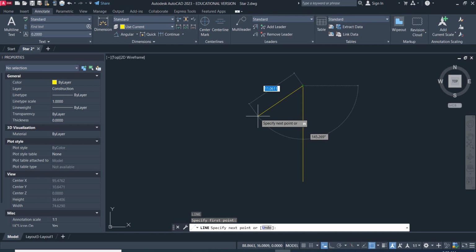We're going to use the line command and our command line down here to type in our commands. I'm going to start with the @ symbol, because that tells AutoCAD that I'm giving these coordinates based on the relative position of the cursor where we started the command. Meaning it's not the absolute coordinate system, but it's relative to the last known point.